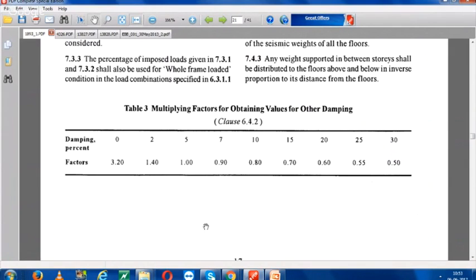For masonry structure, we used to consider damping 10%. For RCC structure, 5%. And for steel structure, around 2%. So now we are having our masonry structure, so you can consider 10% of damping. So value is 0.098. Okay, this is how you need to calculate.